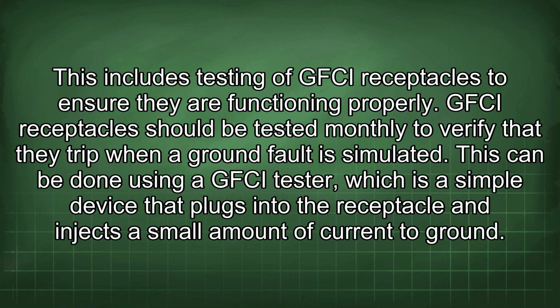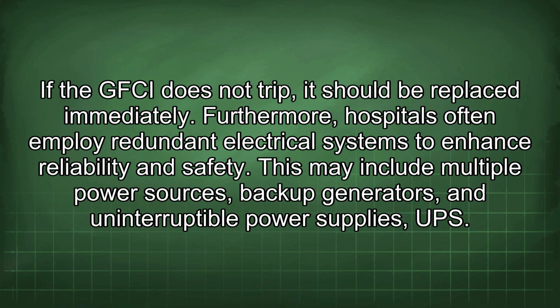GFCI receptacles should be tested monthly to verify that they trip when a ground fault is simulated. This can be done using a GFCI tester, which is a simple device that plugs into the receptacle and injects a small amount of current to ground. If the GFCI does not trip, it should be replaced immediately.